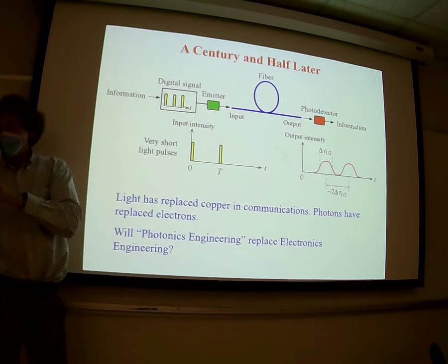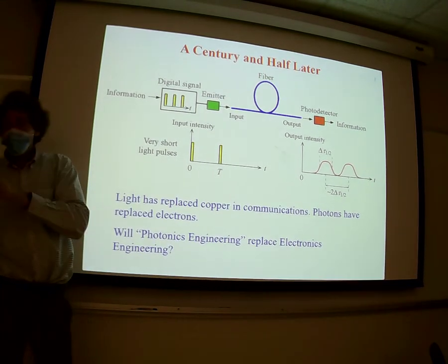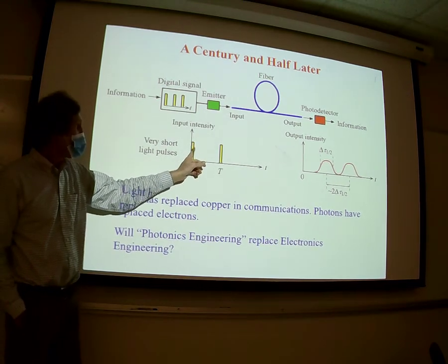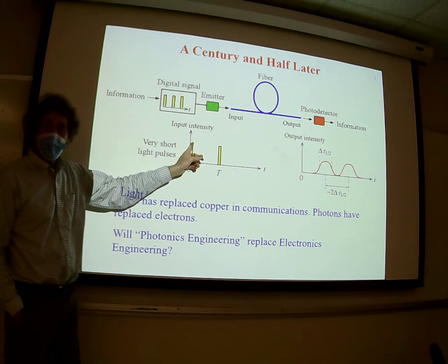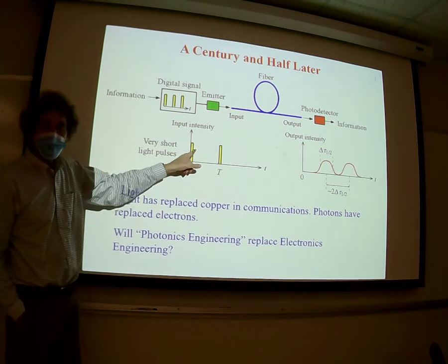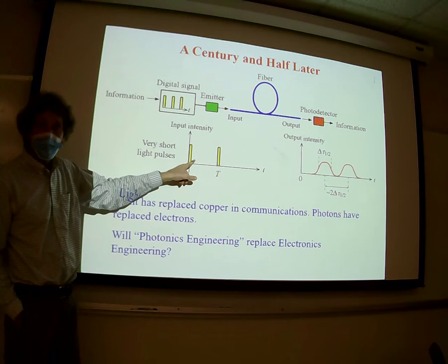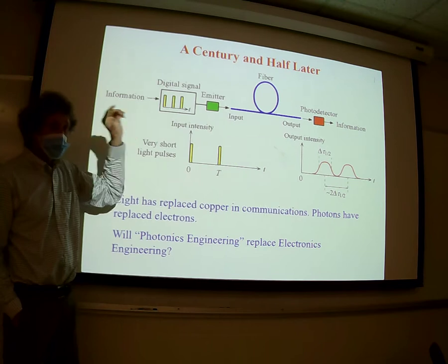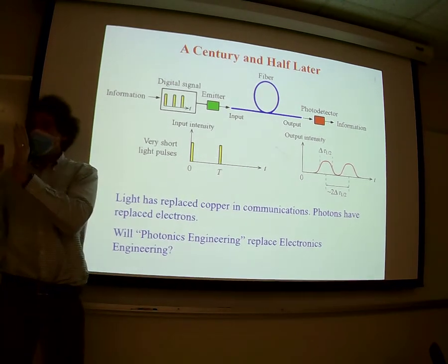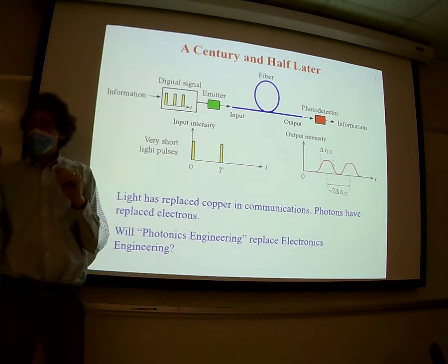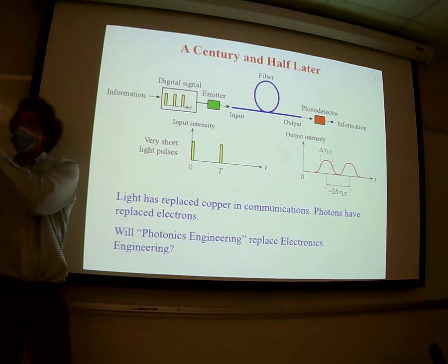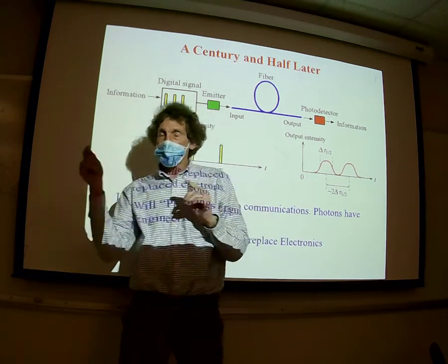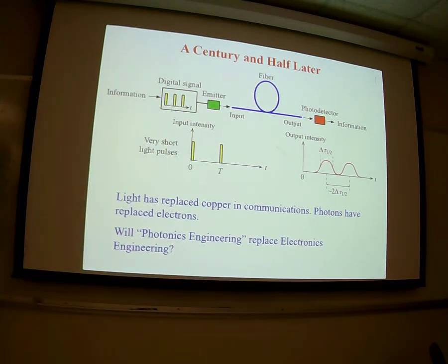What you don't get, remember this, unlike AM and FM transmission, is a carrier superimposed on that. You don't get something where the amplitude is modulated. The only thing you get is digital packet information. Y'all follow me? This is real important. So they send a burst of information, then it's dead. If you took a snapshot in time of a fiber optic cable, you would see a whole bunch of photons, then no photons, a whole bunch of photons representing the packets going down it.